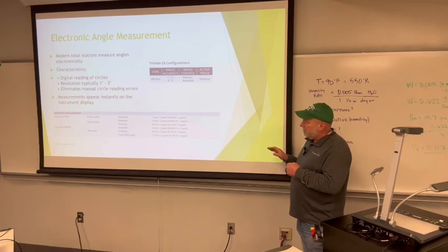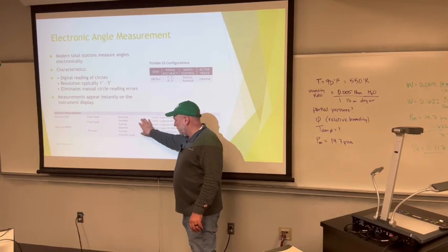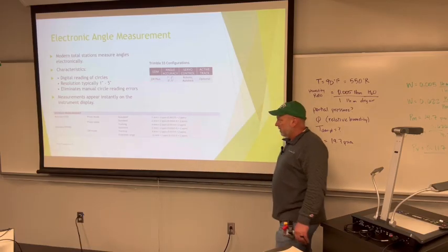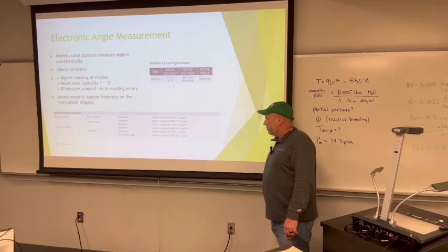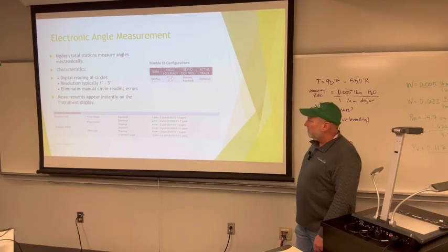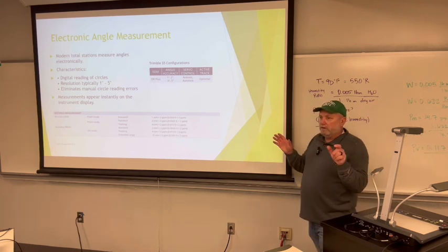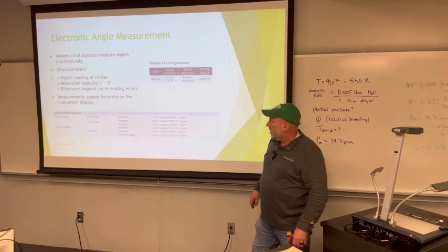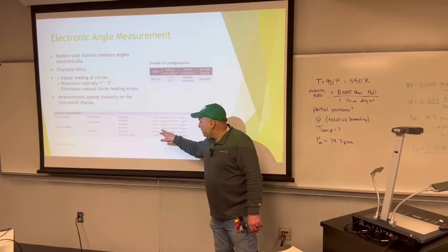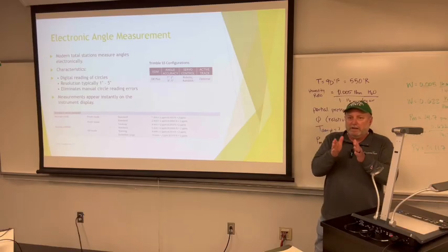Now we talk about some distance measuring. Here are the precisions that the TSC5 is capable of. With your prism in the standard mode, you're looking at 1 to 2 millimeters plus 2 parts per million. So you have a constant, you have a scalar amount there. In prism mode, standard and tracking, your tracking goes up to 4 millimeters. So instantly, you're going to be off that much.